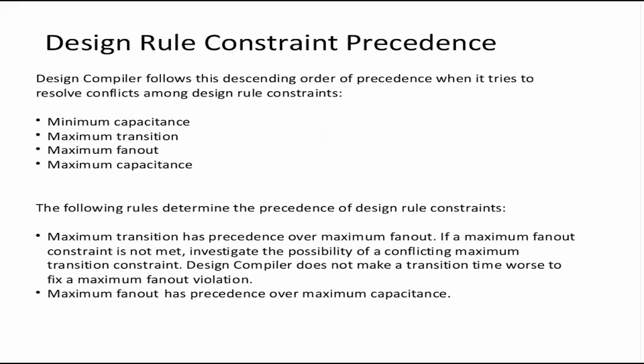So the important point to note is max cap makes sense for the output pin of a gate. Max trans is the limit imposed on the input pin of a gate. You can verify this by opening up the library, seeing the .lib file. Please verify this point, where the max cap attribute is defined, where the max trans attribute is defined. Fan out load represents the load presented by the fan out of the cell.